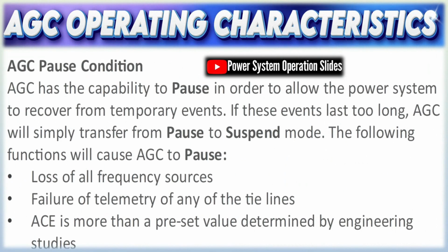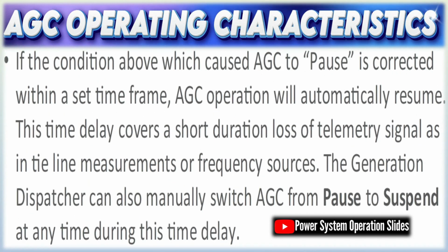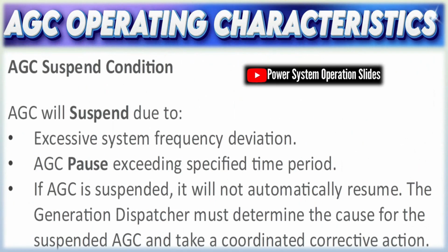Tie line bias control: this mode blends both objectives by considering a bias factor. The control error is a linear combination of frequency deviations and tie line power errors, meaning that both parameters guide the control actions. The frequency bias factor here is critical for ensuring that the control action appropriately reflects the grid sensitivity to frequency changes.